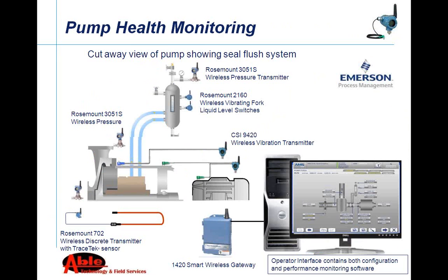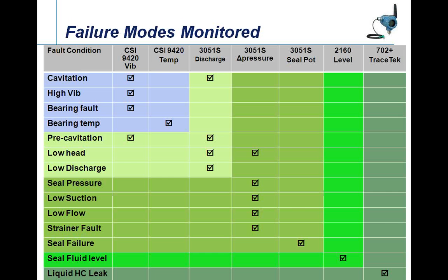If you look at the pump health monitoring available, it goes well beyond vibration. You can see here you can apply monitoring that is appropriate to you, whether it's vibration or whether it's on your seal water levels, your seal system levels, discharge or suction pressures. All are available, and you pick and choose what you need for your particular application.